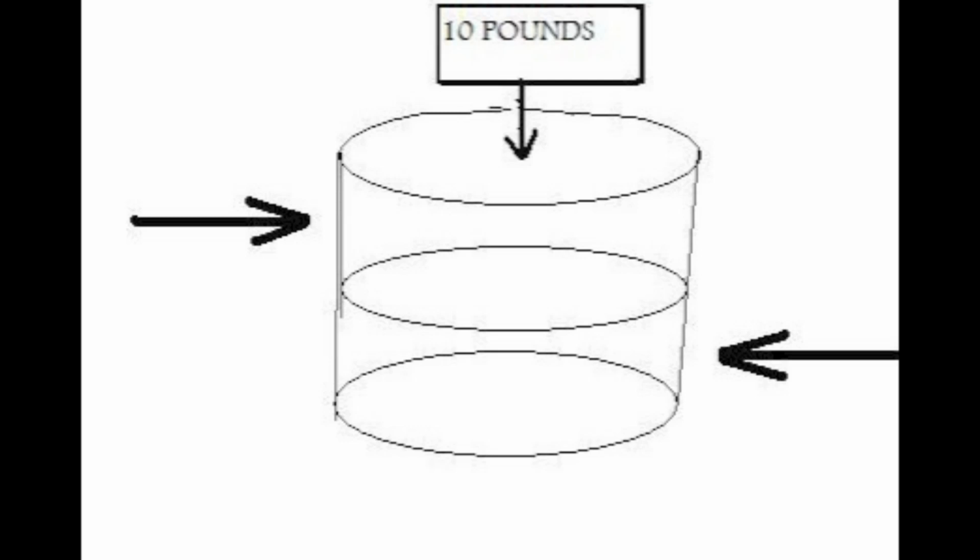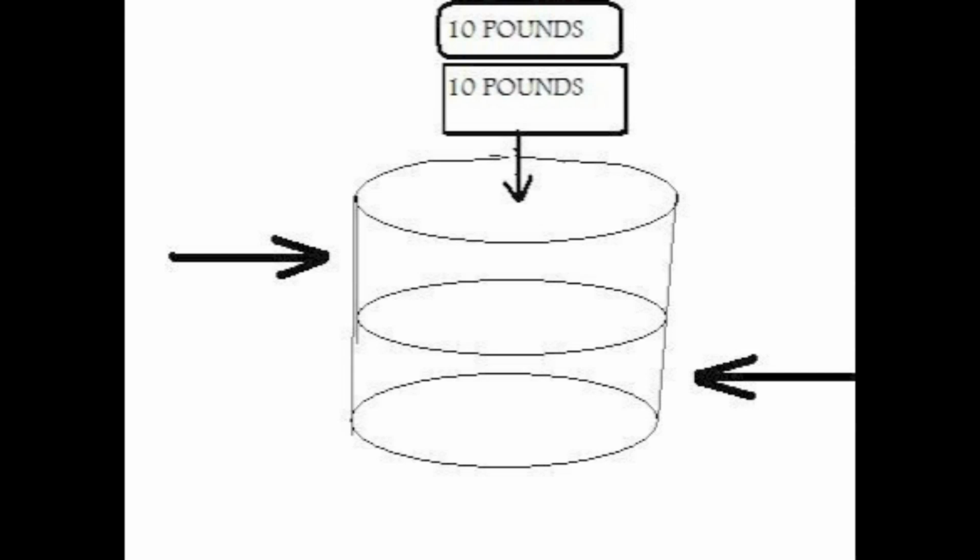Here's a simple depiction of a shear sample. Imagine a 10-pound load applied to the top of the specimen. Then the soil is sheared horizontally. Its ultimate shear capacity will be dependent upon the load above. Now if we add another 10-pound weight on top of the specimen and run the test again, the soil's ultimate shear stress will increase from that of the previous run.